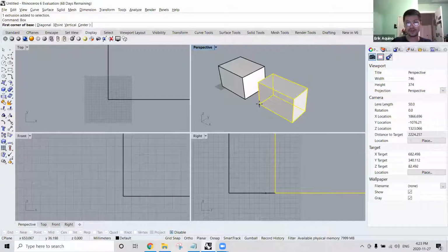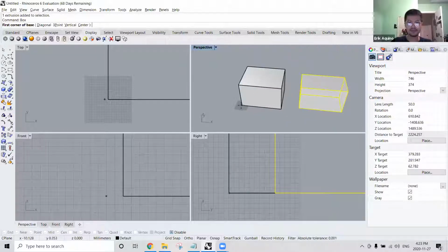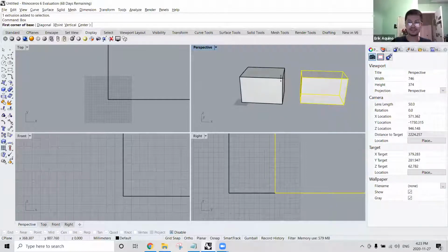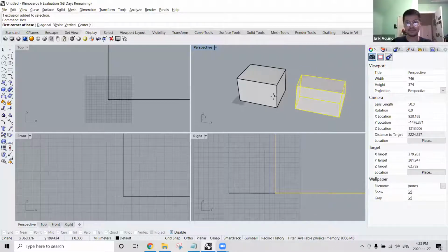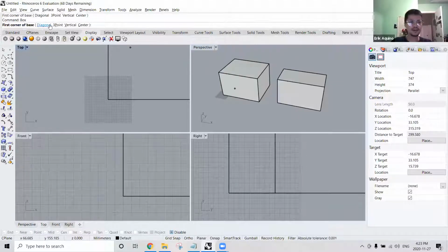I got to choose the length, the width, and the height, versus here, by default, I'm creating the base rectangle for a box and then determining the height for that. So I suggest that when you're learning these commands to take a look at what are the options for every instruction to see how you could further modify your objects.